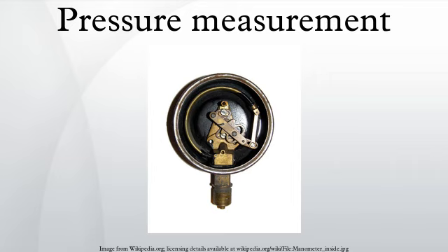An absolute pressure measurement is one that is referred to absolute vacuum. The best example of an absolute referenced pressure is atmospheric or barometric pressure. To produce an absolute pressure sensor, the manufacturer will seal a high vacuum behind the sensing diaphragm.